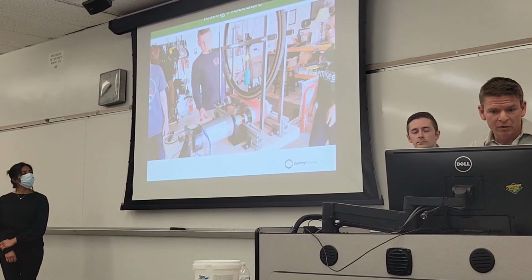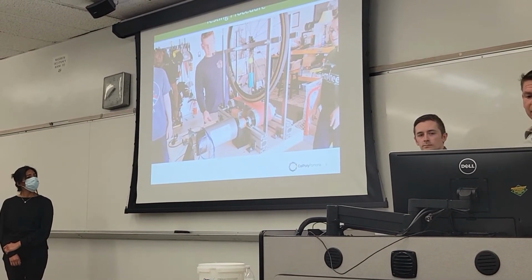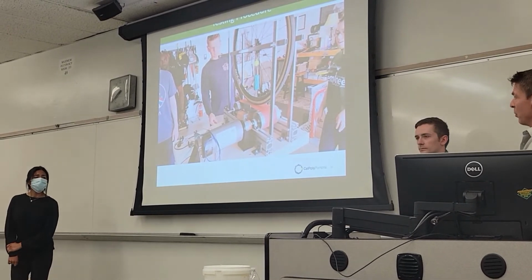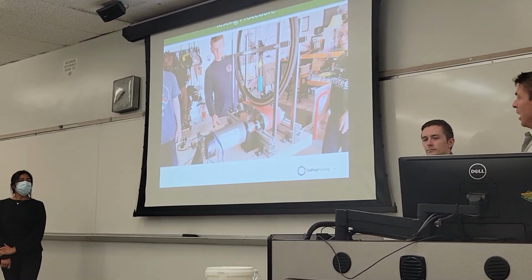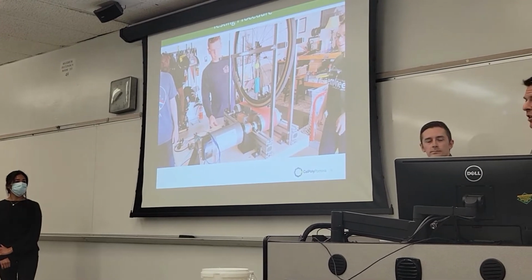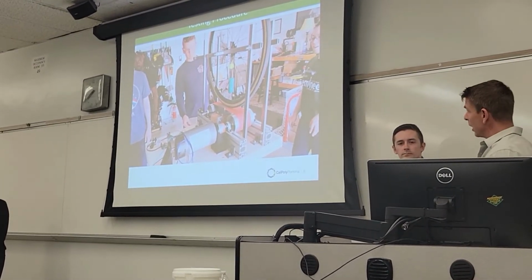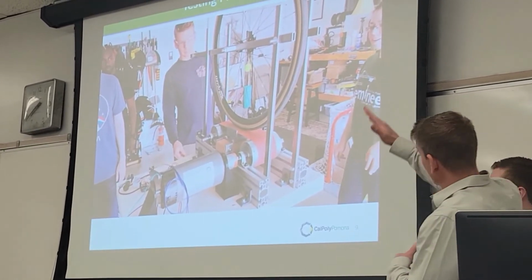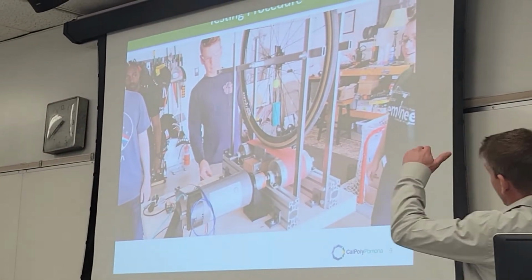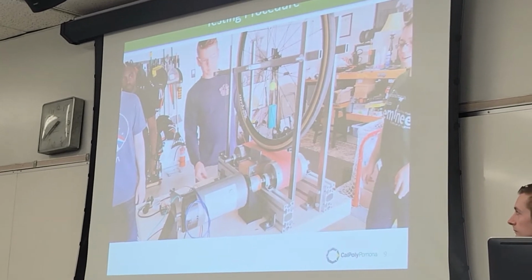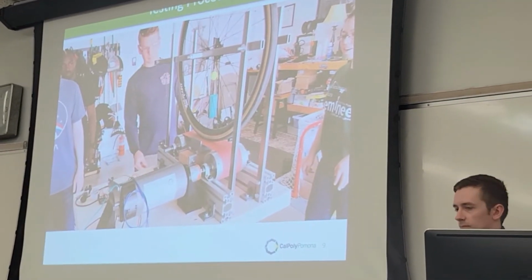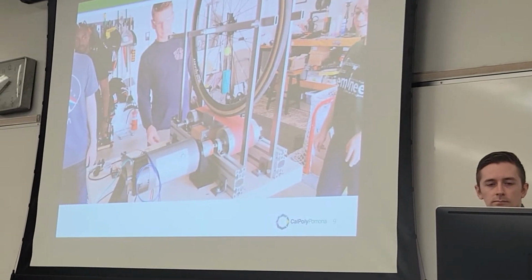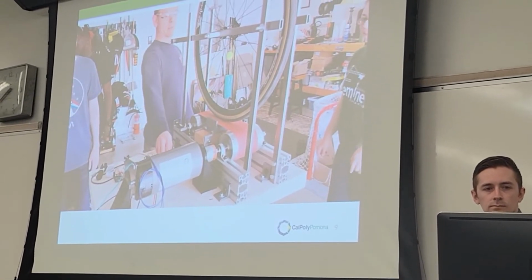So for our testing procedure, to start off, we ensure that the system is aligned, the pulley wheels are aligned, and then we apply tension to the belt. We load the wheel. The wheel mount actually rotates down, so we load the wheel onto the wheel block, and then we apply the weight. The data acquisition is started, and then the system is started gradually.